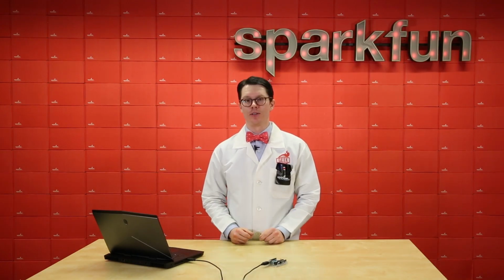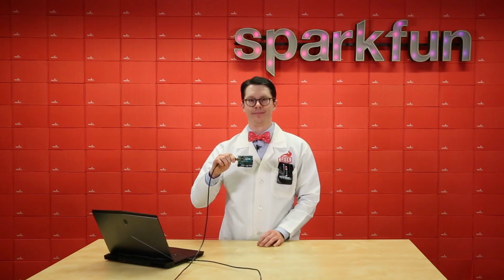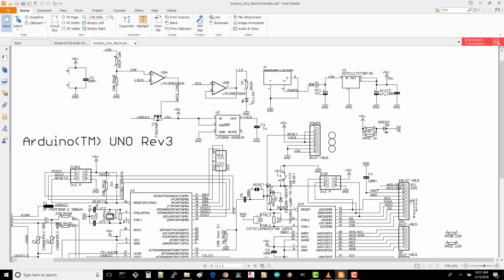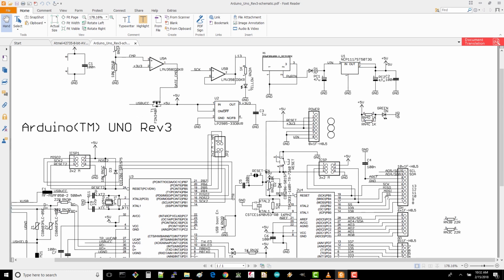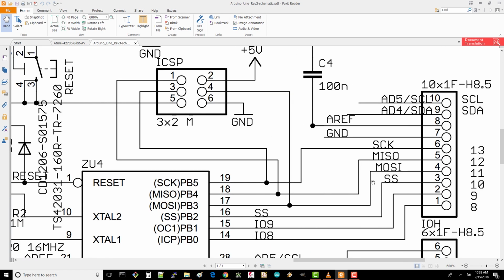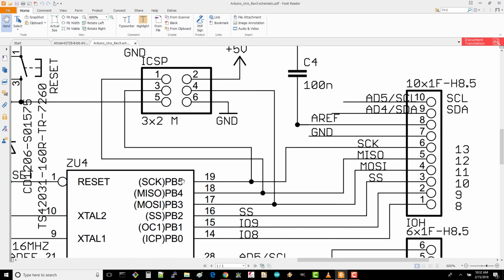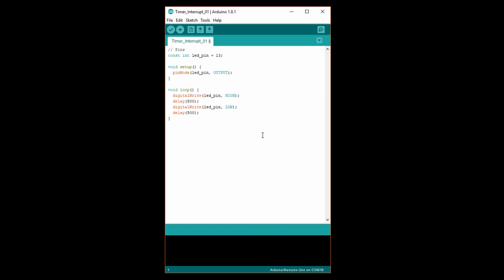of an unknown signal. To see how to set up timer interrupts, let's look at an example that is the classic Blinky program. To do that, you will need an Arduino with an ATmega328P, such as the Uno or Redboard. We'll be using pin 13 this time, as it's already connected to an onboard LED. Notice that Arduino pin 13 is actually port B pin 5 on the 328P. We'll start with this simple example.